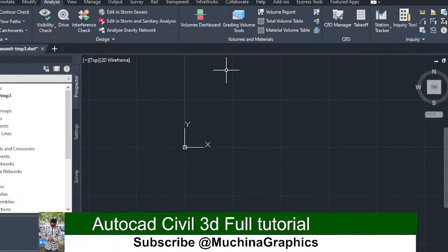Because for example, if a road is being designed in an urban area, and then you have a lot of cuts, you have a lot of fill, but the material that you are cutting out cannot be used. Even if you stabilize the material, it cannot be used. So then what do you need to do? You have a lot of work to transport material, to borrow materials from other areas, and also to transport your material from the existing area to another dump site.